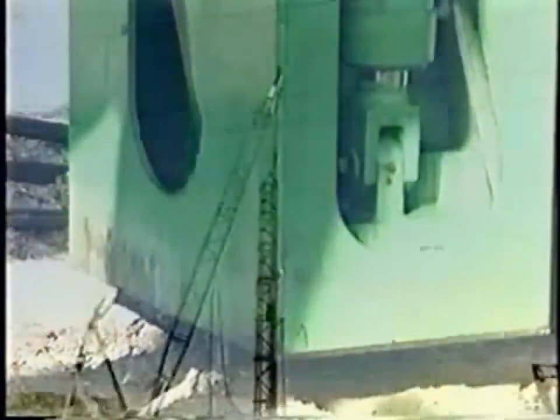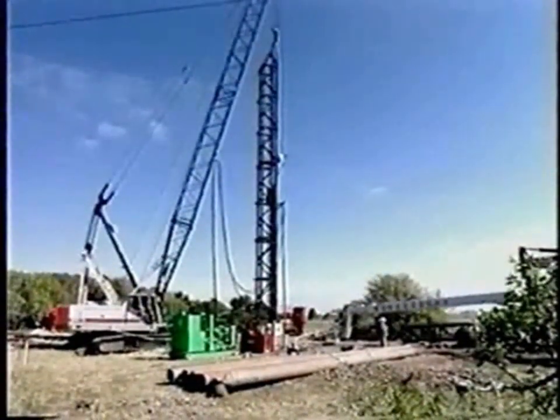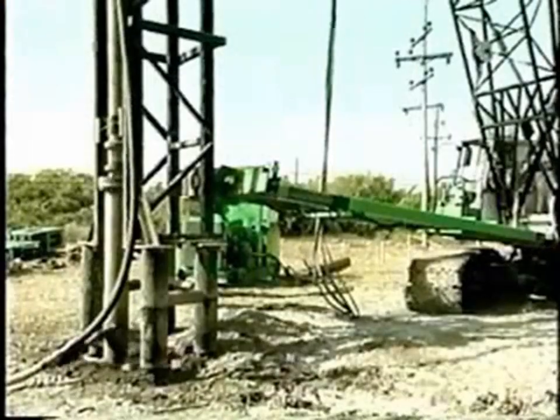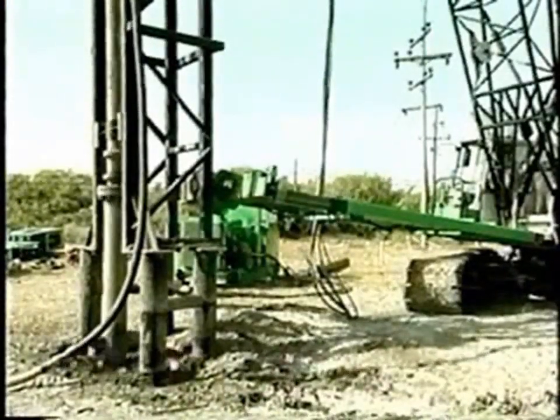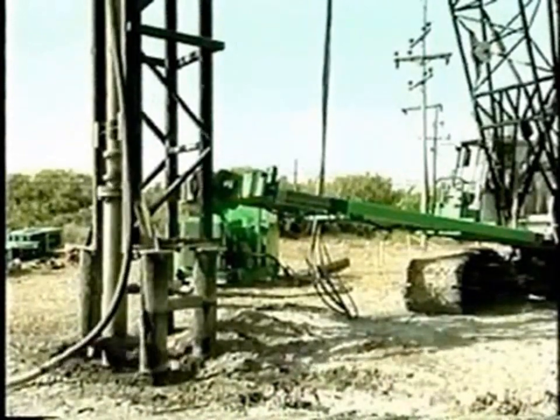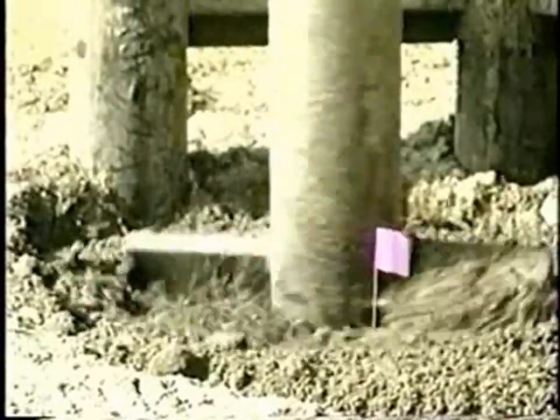To begin the deep soil mixing operation, a 4-foot diameter rig is mobilized to the site. An auger mounted on a guided set of rails is lowered 40 feet into the ground. It functions much like a cake mixer, blending the columns of zero-valent metal with the native soil.